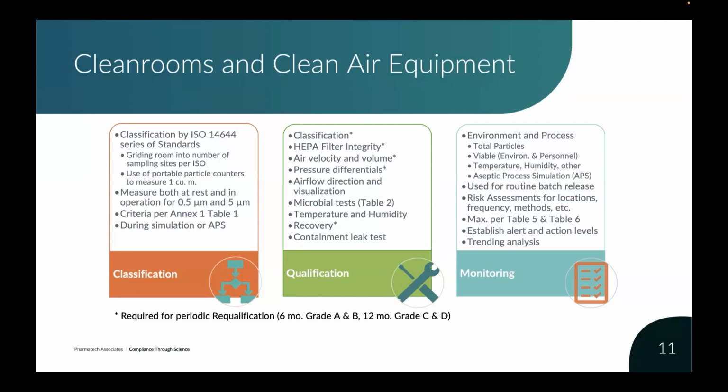That portable particle counter is designed to measure 1 cubic meter of the air over a fixed time that's defined by the ISO to make a measurement of the particles in that particular space of the grid. You have to measure under this Annex 1, as we understand, both at rest, which means all equipment in place but not operating and personnel not in the clean room, and in operation for both 0.5 micron and 5 micron. That's the requirement under Annex 1, although ISO